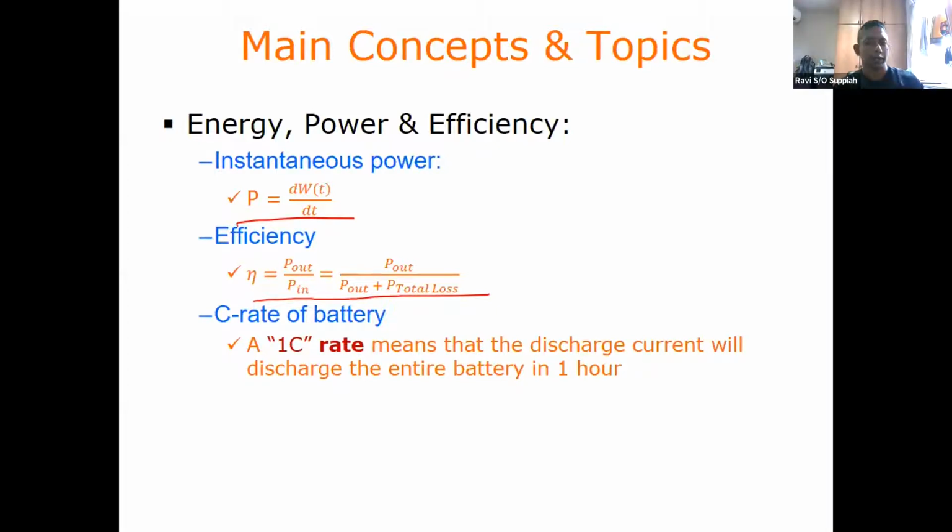The alternative is what one of your friends shared today, the efficient PWM signal. Using a PWM signal, you vary the voltage, which in turn affects the current, and we can get the required color with higher efficiency.